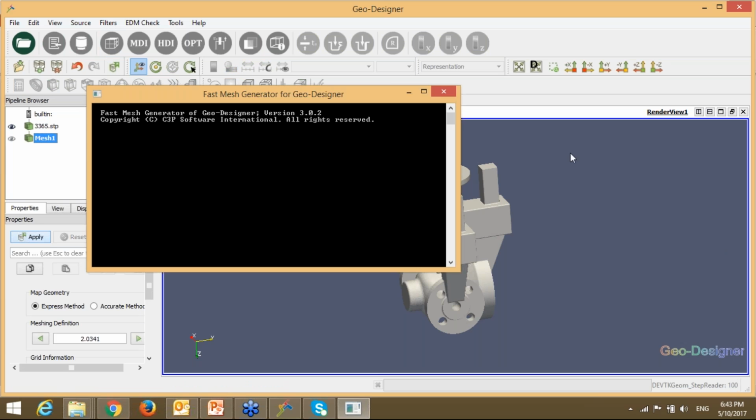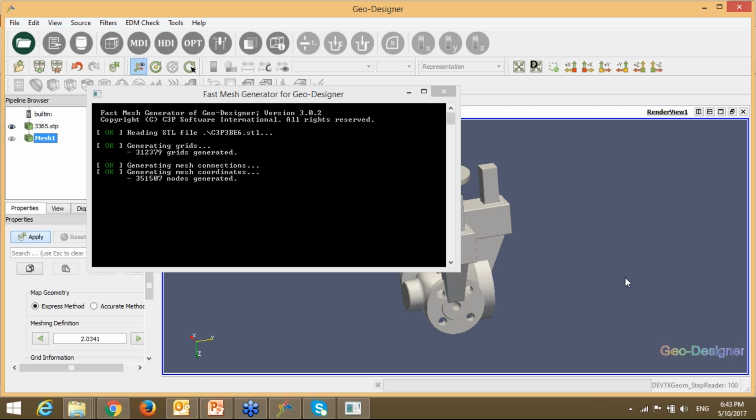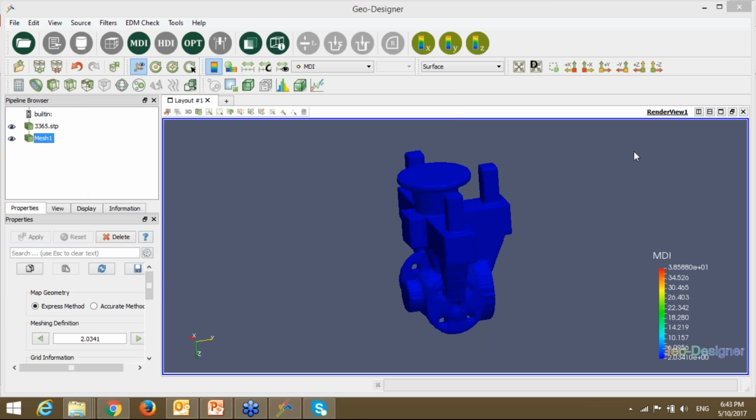There is one more question coming from participants. What are the advantages other than the cost part? Yes, the advantage other than cost is that it will drastically reduce your time in deciding where you will require a riser, or an exothermic sleeve, whether a cheap basic exothermic sleeve will work, or we require a high-end exothermic sleeve which is more potent but costly to address this location.